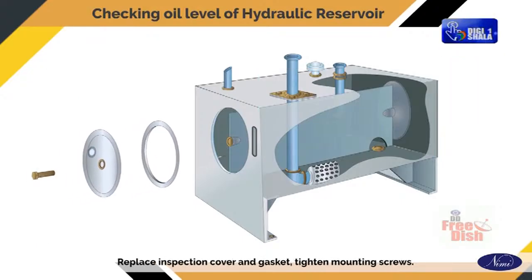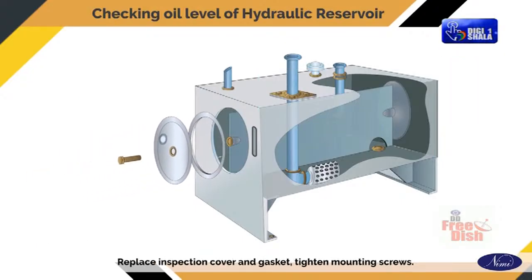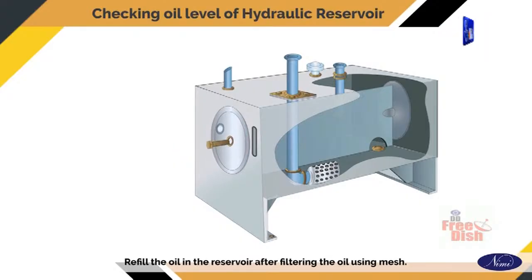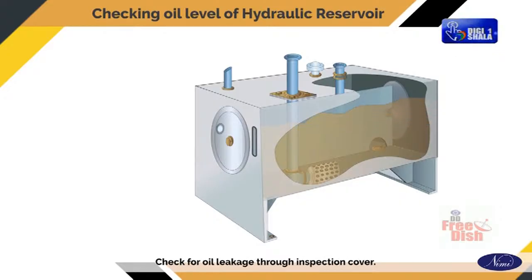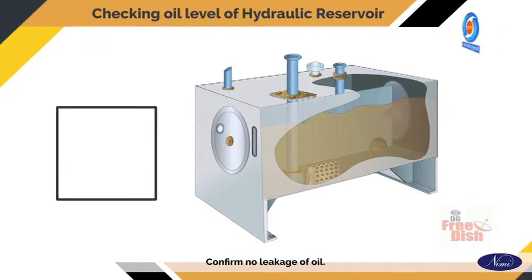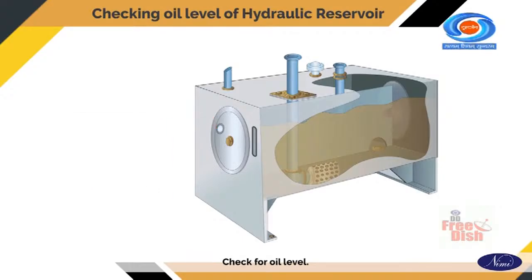Replace inspection cover and gasket. Tighten mounting screws. Refill the oil in the reservoir after filtering the oil using mesh. Check for oil leakage through inspection cover. Confirm no leakage of oil. Check for oil level.